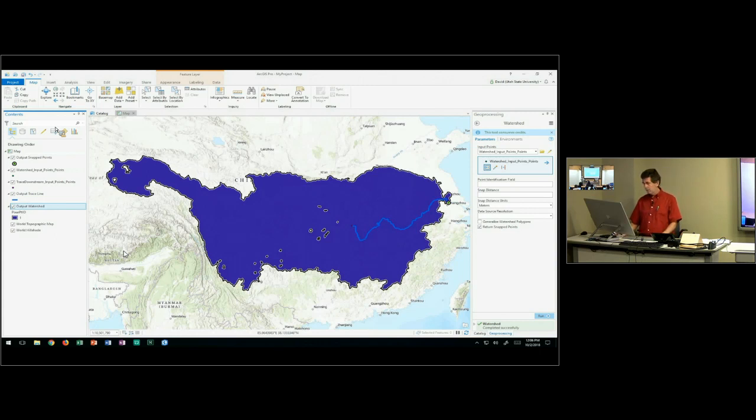If somebody knew whether this was correct or not, we could get confirmation about that. Notice that there are a few gaps inside here. Those are internally draining areas that, for whatever reason, did not have their sinks filled, probably because they are real internally draining areas that were too big, where the water just disappears into the ground.